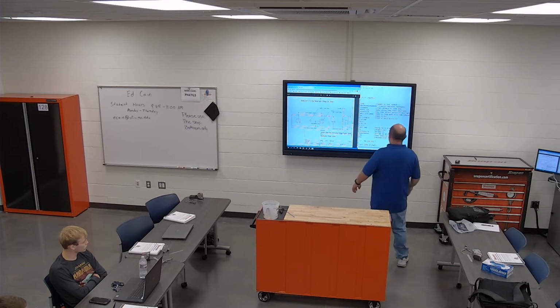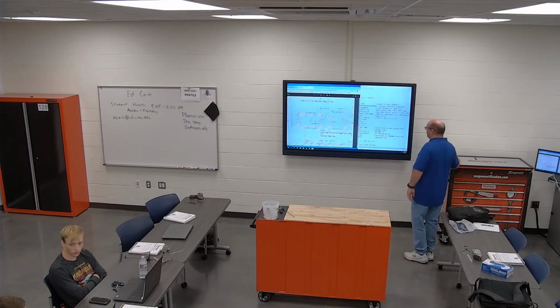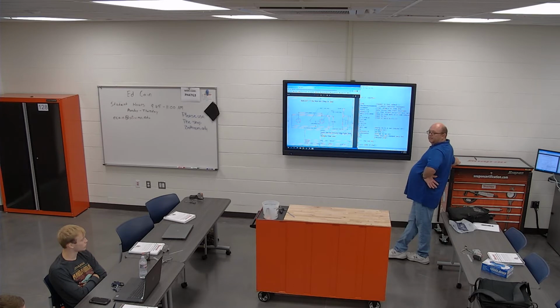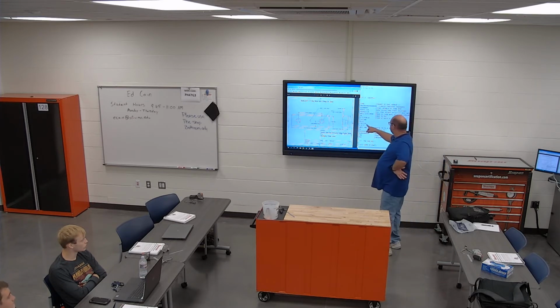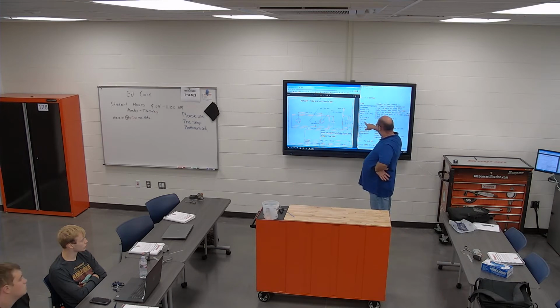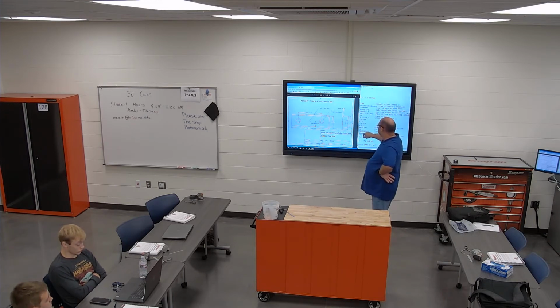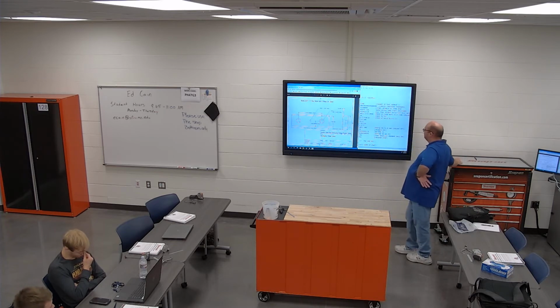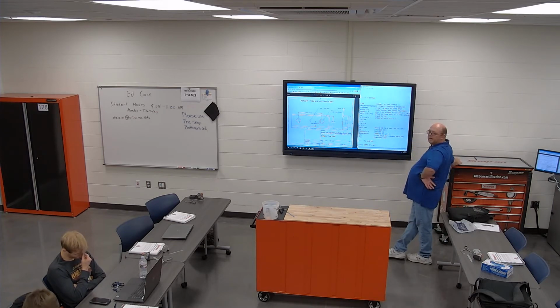Now, even if you wanted to, you could just add an additional line in there to change the feed rate or the speed of the spindle to get a better finish on your last pass. All you would have to do is take this F, feed rate, and put it right here, and it's a changer. Or right here. You have to put it in either the line before or the line of the moving. The line of would be the best.